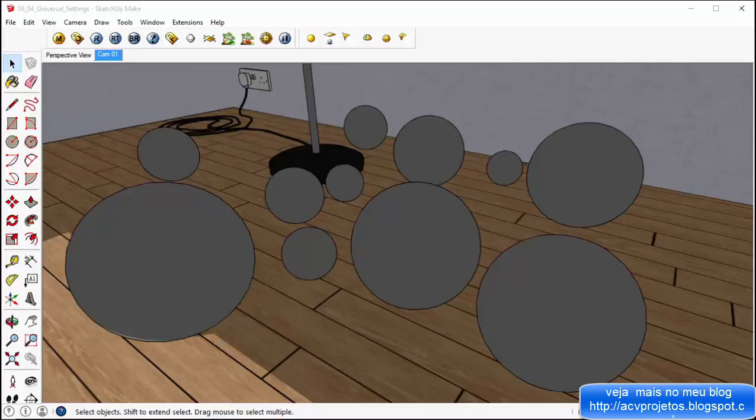The lack of optimization tends to mean that these settings are best employed when rendering stills. If we have a 500 frame animated camera sequence that will take 50 minutes a frame to render using the universal approach, but that with a little bit of tweaking we could get down to say 15 minutes a frame, well, I'm sure you see the potential drawback of sticking with the universal approach in any kind of animated situation.